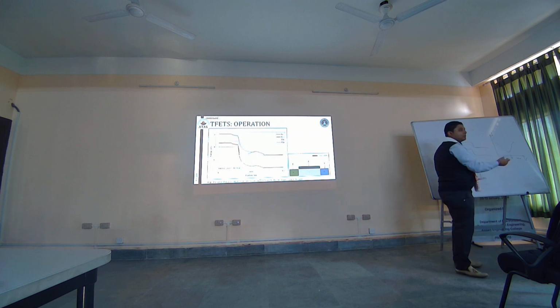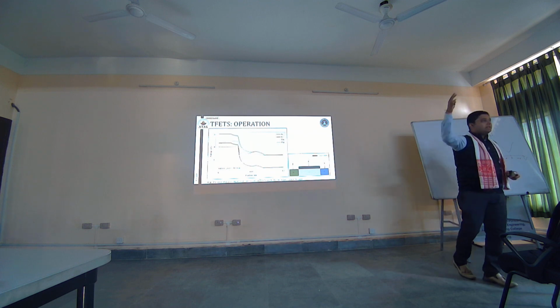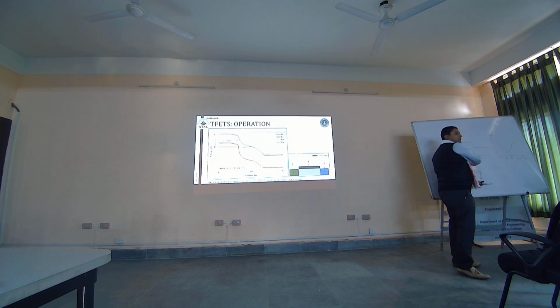You have an appreciable amount of current. So there will be a short path from VDD to ground because your P type is also conducting in your negative voltage, assuming that it is plus by potentials. So it will not act as a CMOS inverter.